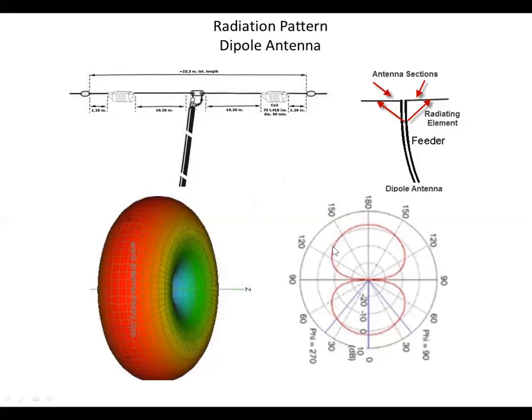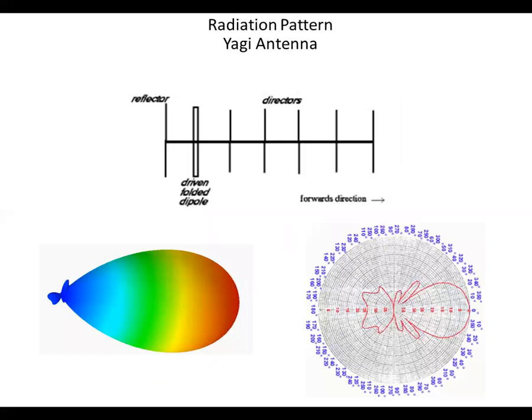The lower this part of the lobe is to the ground, the more ground wave you have. And for DX and things that are pretty far away, you like to have a low takeoff angle. So it just depends on what you want to do and what kind of antenna you want to use, because the propagation pattern would be one consideration in your decision process.